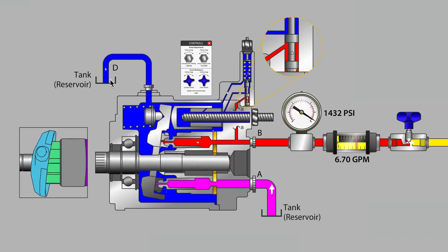Manufacturers recommend a maximum amount of back pressure present on this line, meaning let's not see this line get too narrow in diameter. It's important not to have a filter that could cause blockage on the case drain line. Always a little controversial to put a filter on the case drain line. Mixed reviews about how that works out. Depends on the pump manufacturer and how carefully the user of the pump maintains that.